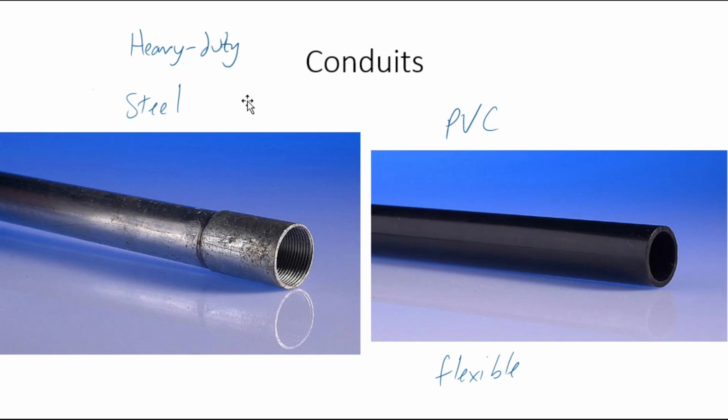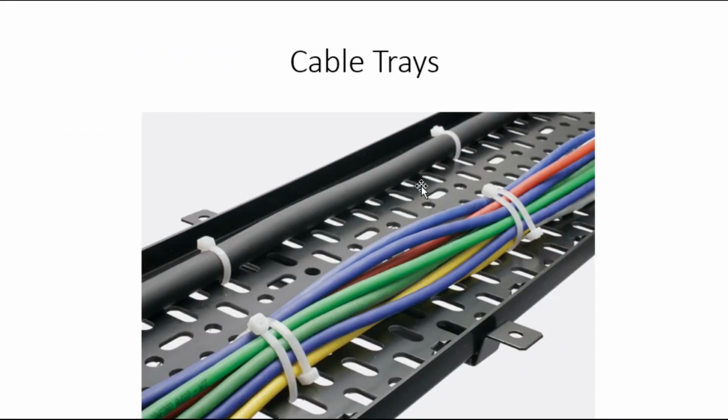In addition to conduits, you can sometimes have trunking systems. These are related to conduits in that they provide mechanical protection of the stranded cables that are passed through them. And finally, we have cable trays. This is a system of installation where there is not likely to be any physical damage encountered or tampering from people.